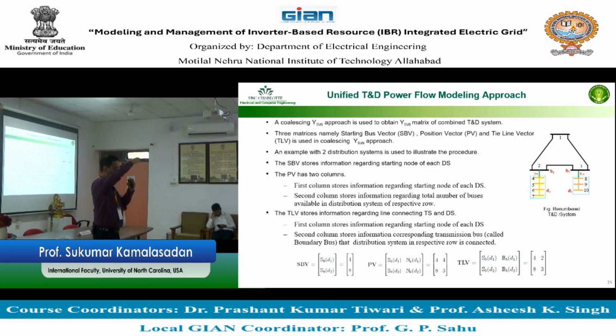And you want to make sure that when this slope shifts, if you may recall, then we draw two parallel lines. So the parallel lines are actually the voltages set by the source of the substation. See, 1.05 to 1.1 to 1, the voltage can vary, right? With all these variations, the distribution should be working well. So you put the voltage regulator and transformer so the distribution line is working well. Then you take that distribution system. For this power flow, you don't really worry about voltages at any of these points. You only worry about the voltage at that point.